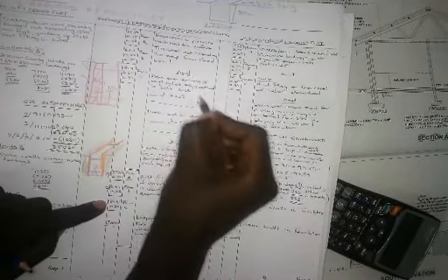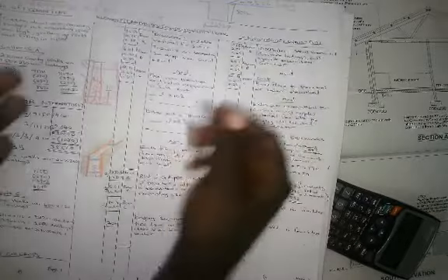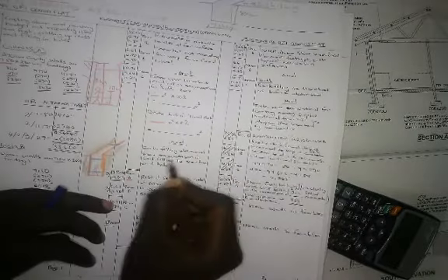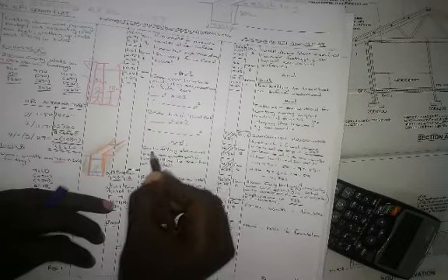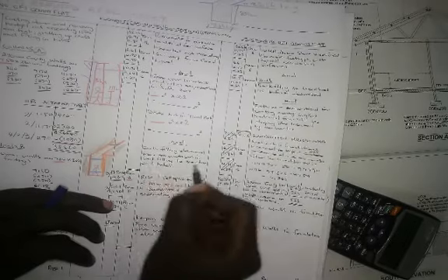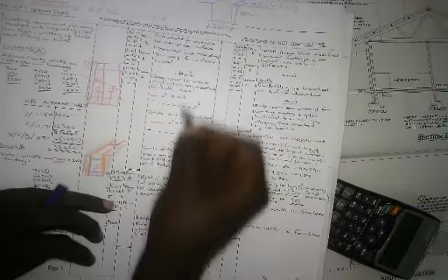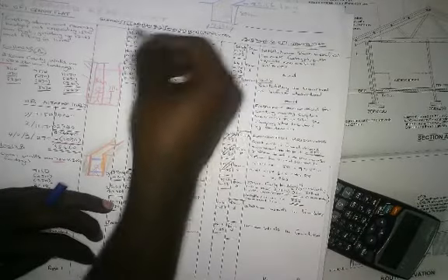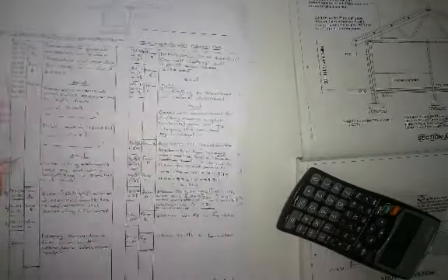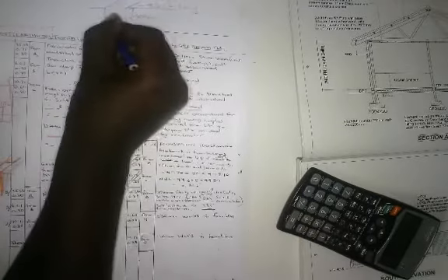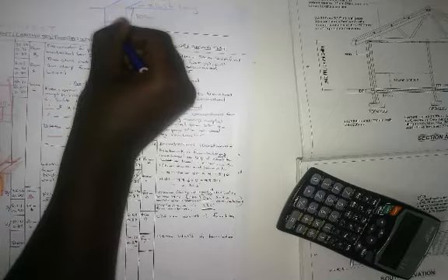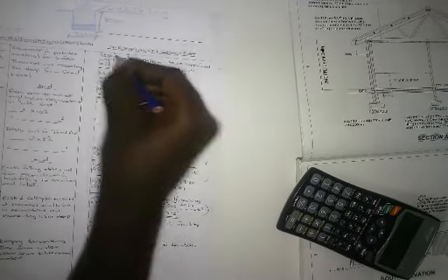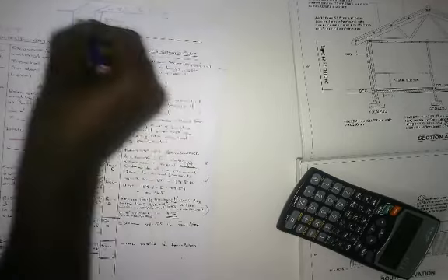So what we did in our first description, we excavated all of this. Then we said extra over for soft rock, and also for hard rock, and then we said backfilling. We said earth filling obtained from excavations, backfilling to trenches. So we backfilled the same cubic amount that we excavated.